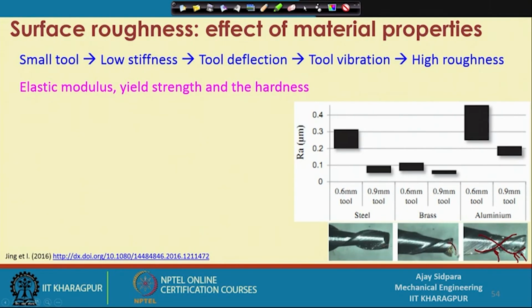And this is in between these two, because here if you see, very small amount of material is loaded in the flute, but this material may be removed if you rotate at a very high RPM. But nothing is here, but the tool wear may be very high in this compared to the other two materials. So, this is the condition of the cutting tool after machining of three different types of workpiece material,